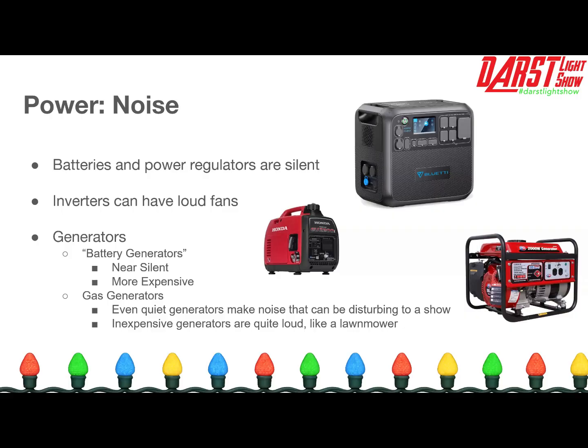So this might detect a cheap Chinese junk power supply as a ground fault, and it'll immediately shut down to protect itself. So every time you go to plug your controller in, your power supply shuts off. Now that's something you can work around. You can test in advance and make sure that's not an issue, but it is something to keep in mind with these battery operated generators.